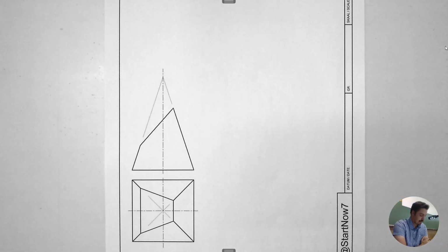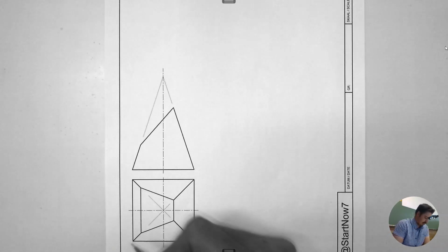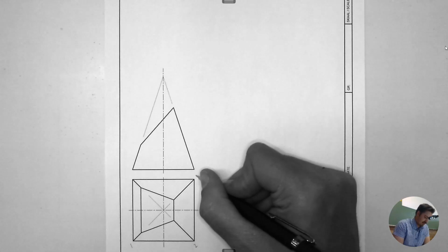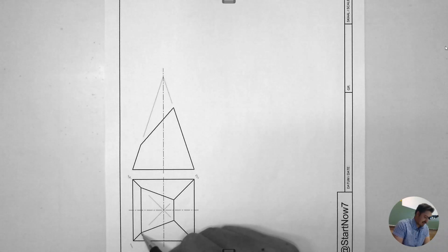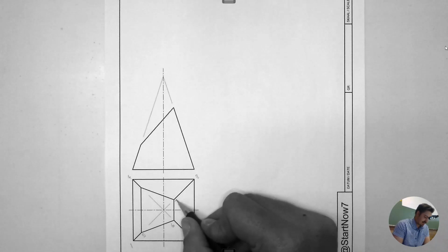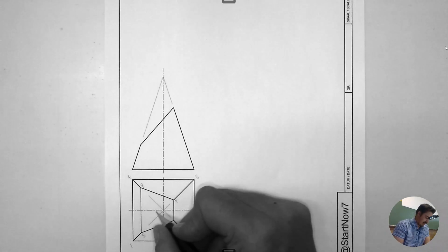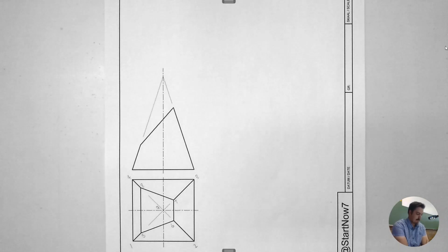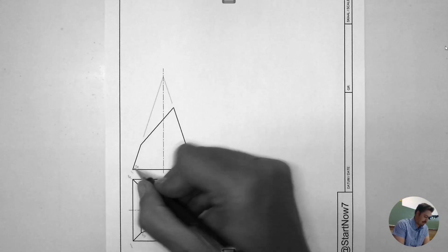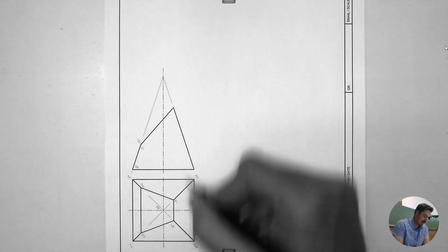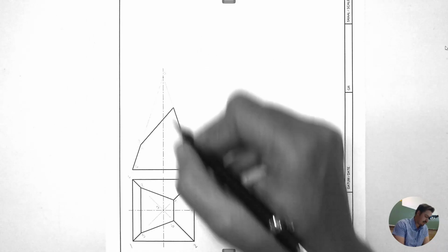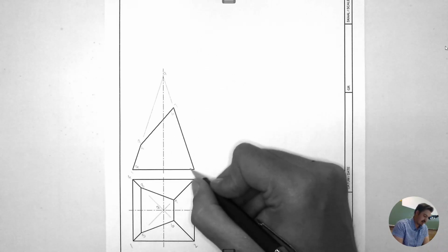So now we are looking at a square truncated pyramid. So the labeling process for this is going to look like this. I'm going to start here, 1, 2, 3, 4, and then I'm immediately starting here, 5, 6, 7, and 8. The middle point of my drawing, I'm going to label something like A. Alright, as this projects upwards, this will be point 1 and 4. This will be 5 and 8. This will be A, 6 and 7, 2 and 3.